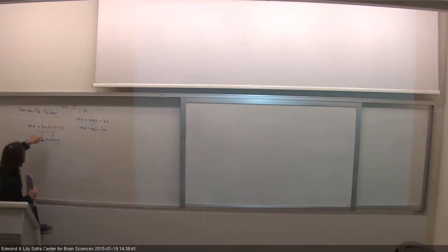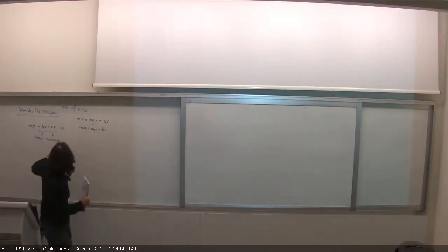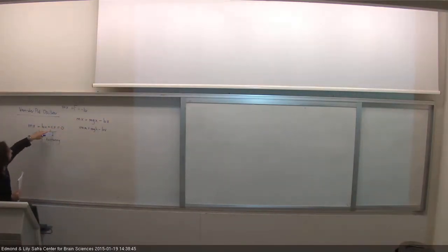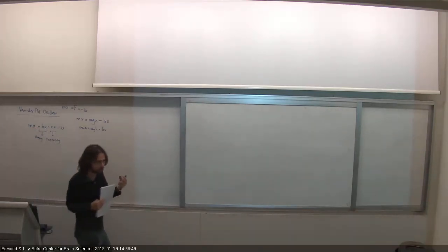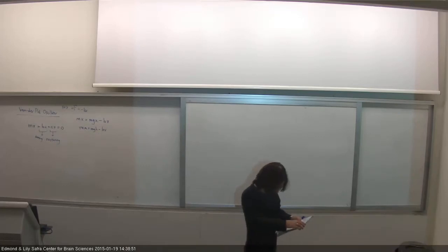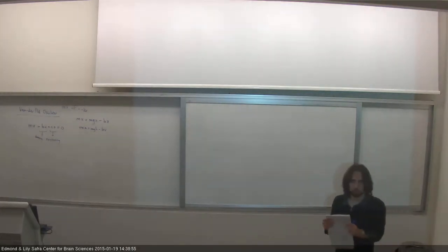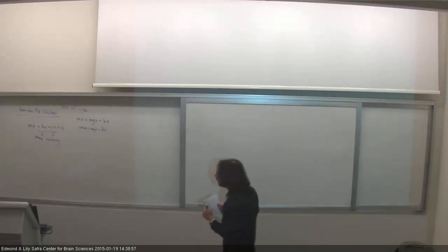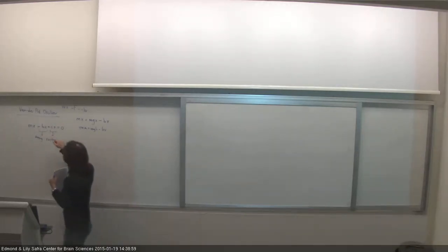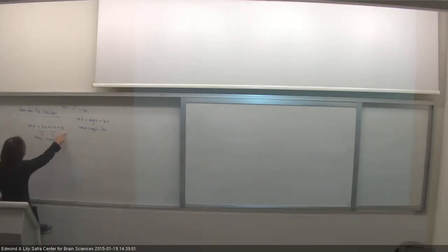Okay, so this is our system. These were just analogies to show you that this is a restoring force, and this is a damping. It's kind of friction on the system. It depends how you write it. If it were here, it would be a minus b, right? So that would actually dampen your system. So a positive b here dampens your system.